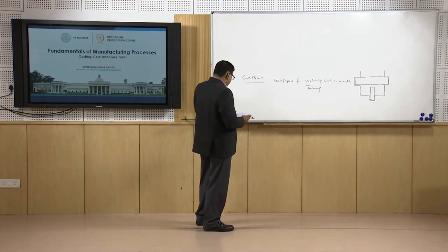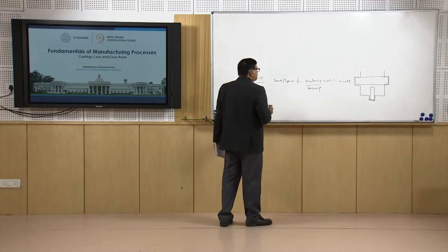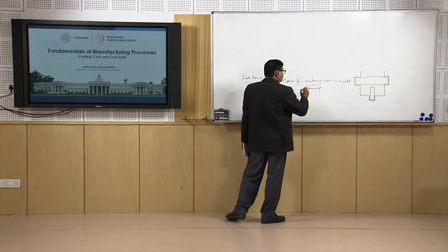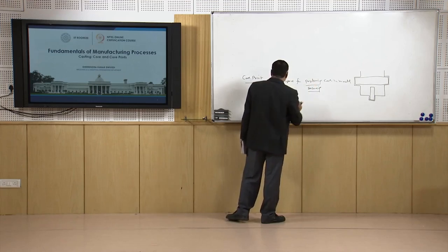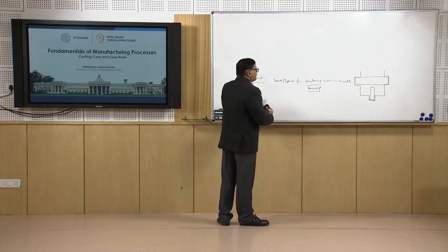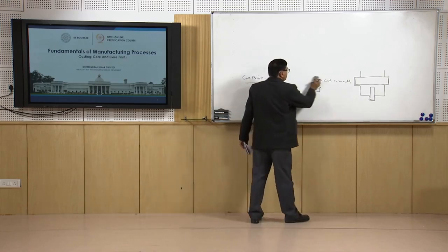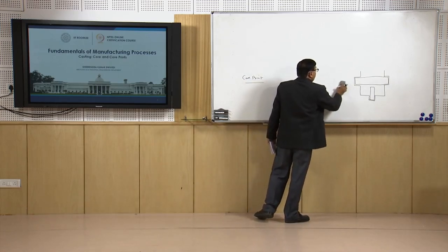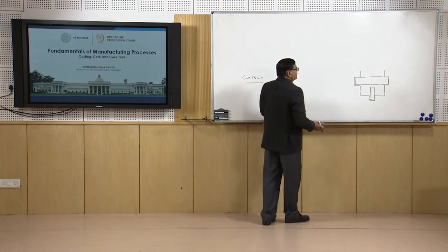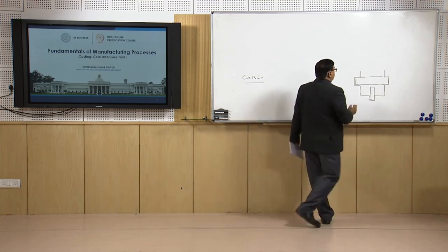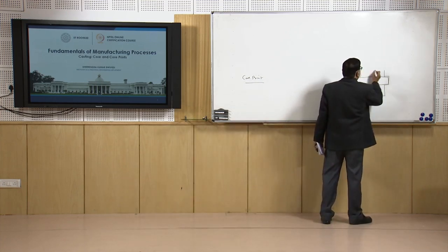So, for this purpose what we need is that it not just positions, but also secures the core in its position, and for that it is necessary to consider the forces acting onto the core, so that you can identify what size of core print is to be used.